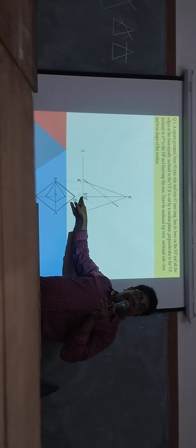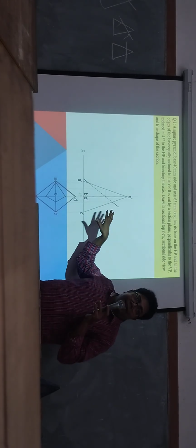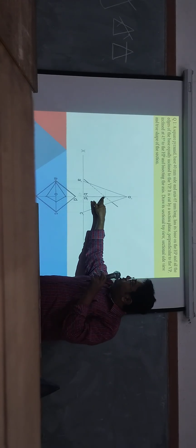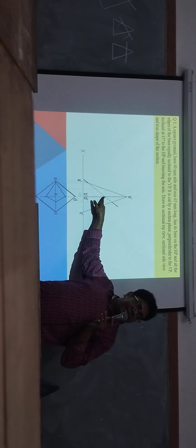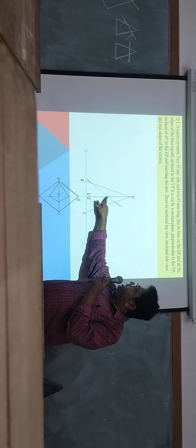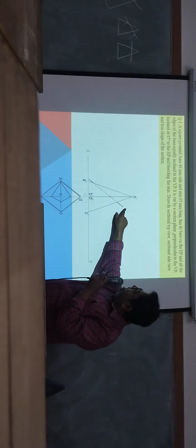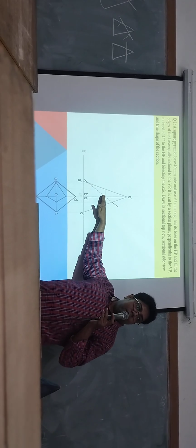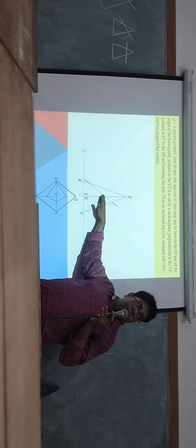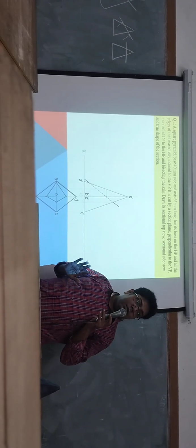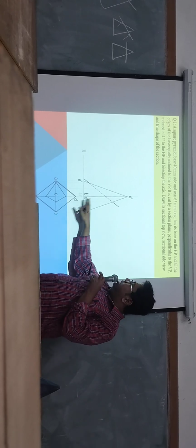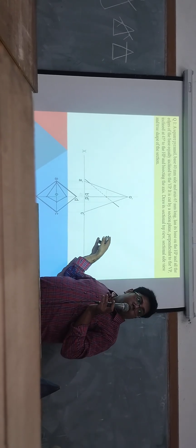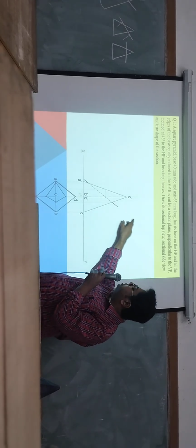Now we have to show the cutting line. That is the cutting plane. In 2D actually it is showing the cutting line. Now find out the midpoint by bisecting this line. To this point you have to draw a line which is making 45 degree with horizontal. If you are unable to make horizontal, just draw a horizontal line from this point, and with respect to that line, you draw it.